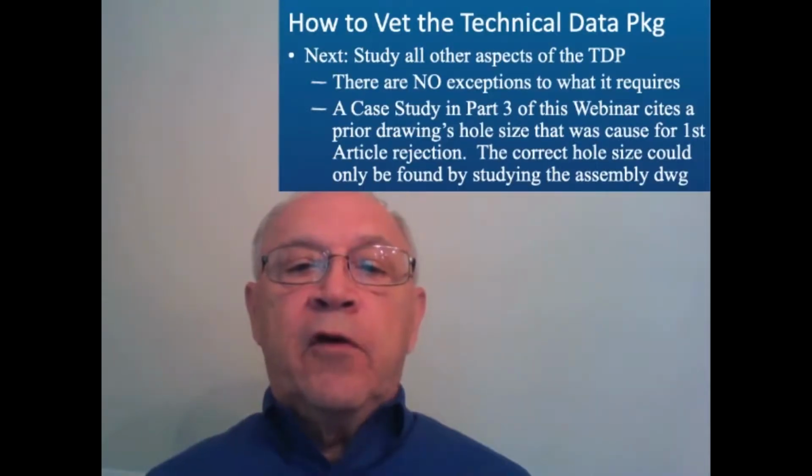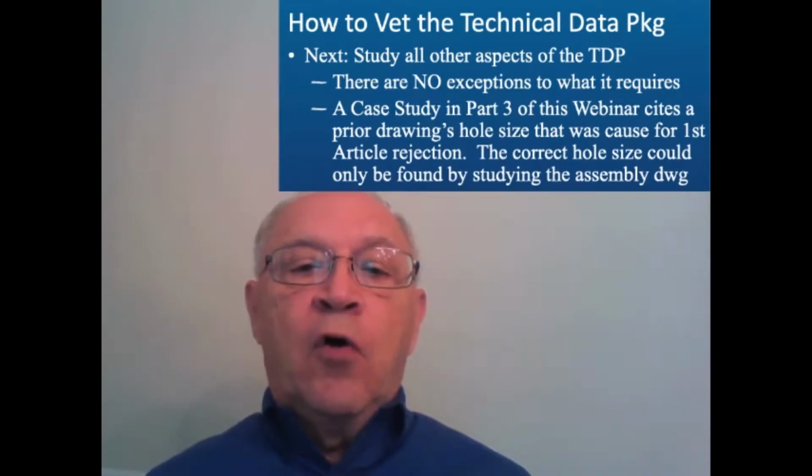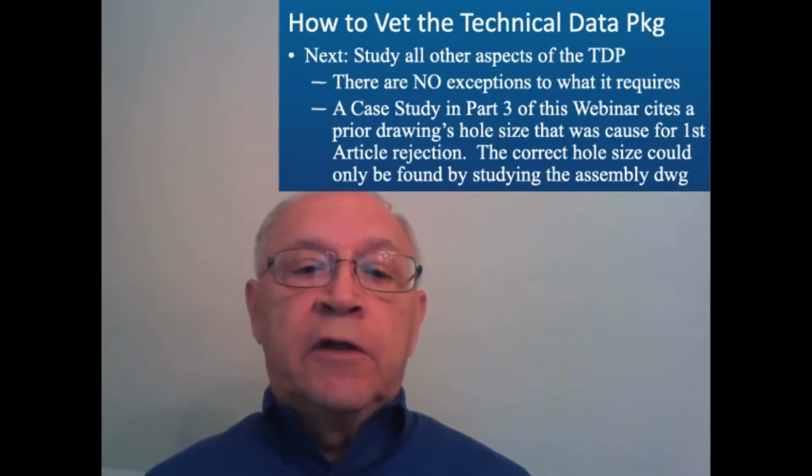Thank you, Mike. Now let's turn our attention to complying with the technical data package. Remember, there are no exceptions to what is required by the TDP. We cover a case study in Part 3 of this webinar series where a purchased hardware piece part's hole diameter was cause for the first article rejection. That was the only cause for the first article rejection. Surprisingly, the correct hole diameter could be found only by studying the assembly drawing, which included a note to drill the purchased hardware part, that attachment hole, oversize.